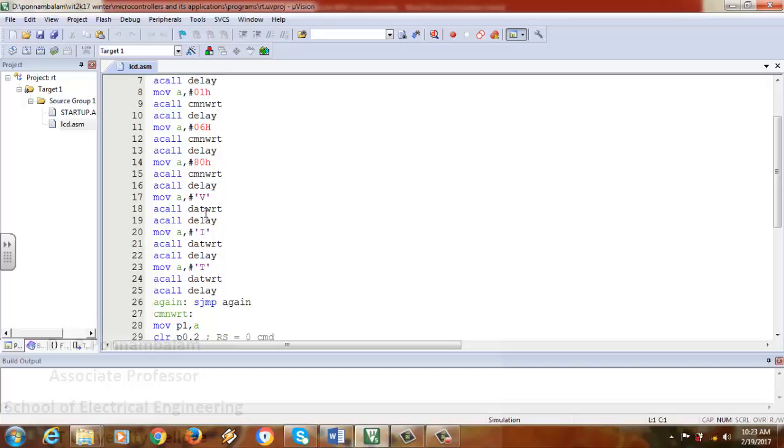It gets into the accumulator as a hexadecimal number, which is the equivalent ASCII code of v, and that is transferred into the LCD screen, and the LCD screen converts the ASCII code into its character. That's the basic idea of the LCD screen, and it's a basic advantage also.